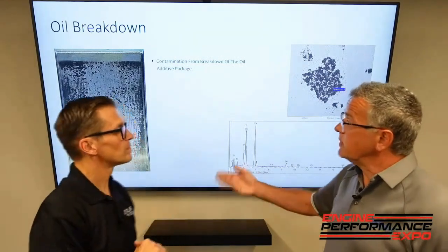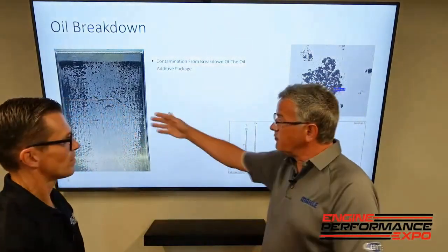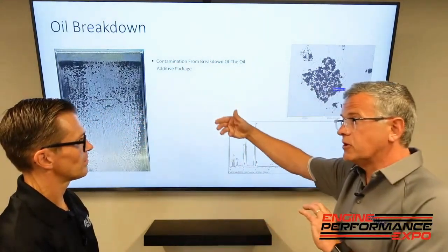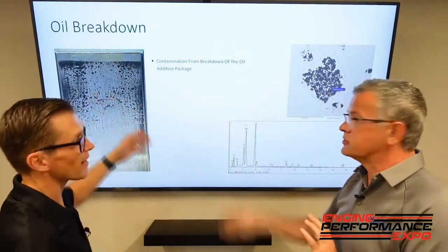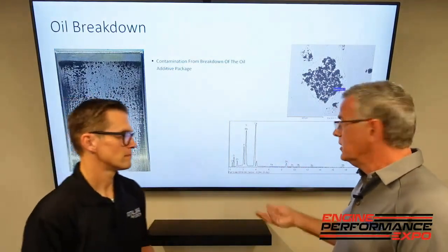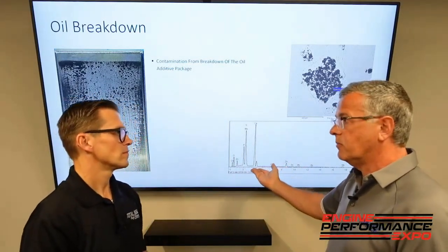Interesting. So basically, if you catch it before, you go from a little bit of wear on the bearings to finally, as we had some of the other bearings, where it just finally is gone. Yeah, it's gone, and you're getting substrate eventually to the bearing that spun and failed, and could have been prevented by just changing your oil.